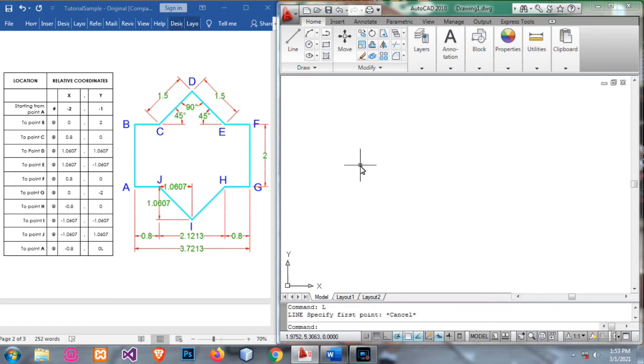Always remember to turn on these drawing modes when dealing with 2D drafting so that we can easily deal with our commands. First, turn on the polar tracking. Next is the object snap. Next, the object snap tracking. And lastly, our dynamic input. So take note of that.